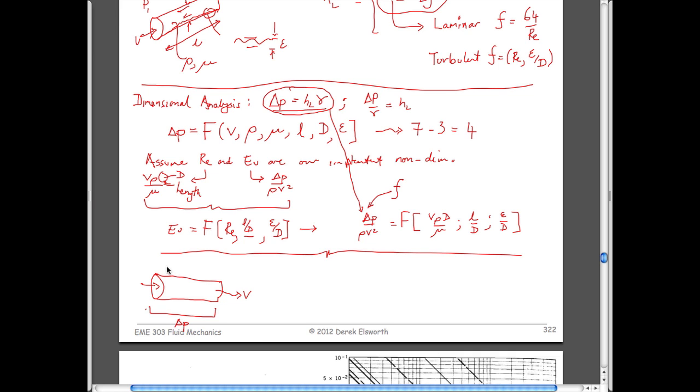And so if we have some length of this pipe, just as we've had before, some diameter of this pipe, as we've defined before, we can actually get the average velocity as a function, I have it written down here, as equal to the diameter squared divided by 32 times the viscosity of the fluid times the pressure change over the length of the pipe, divided by the length of the pipe. And so that's just a solution.